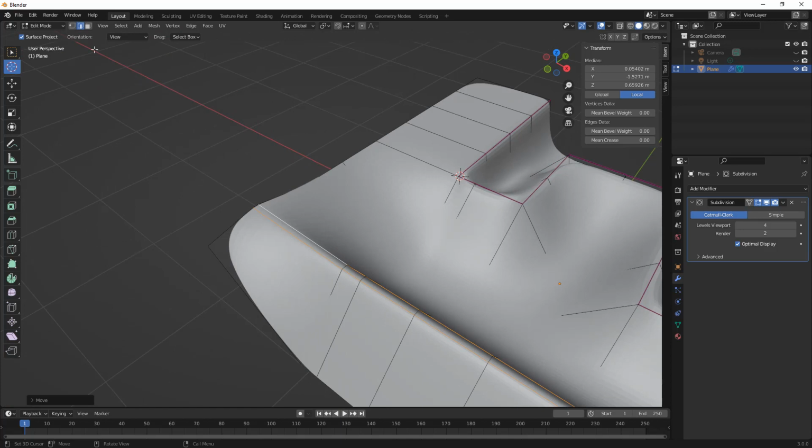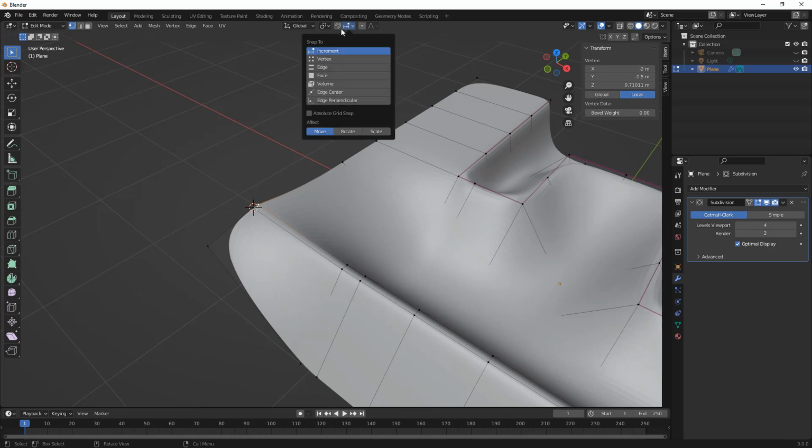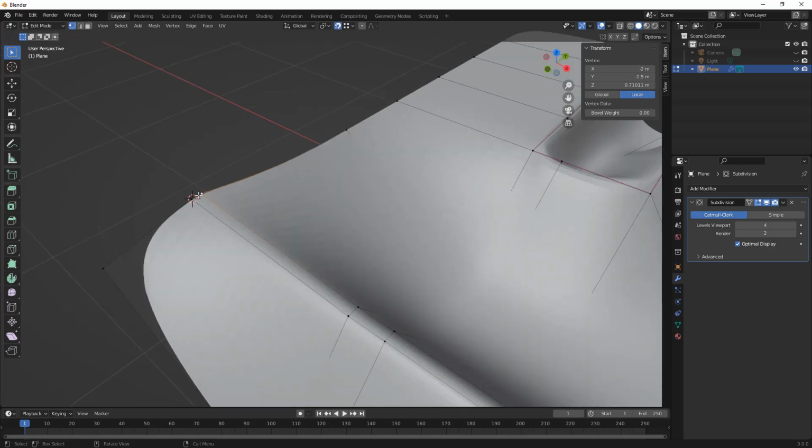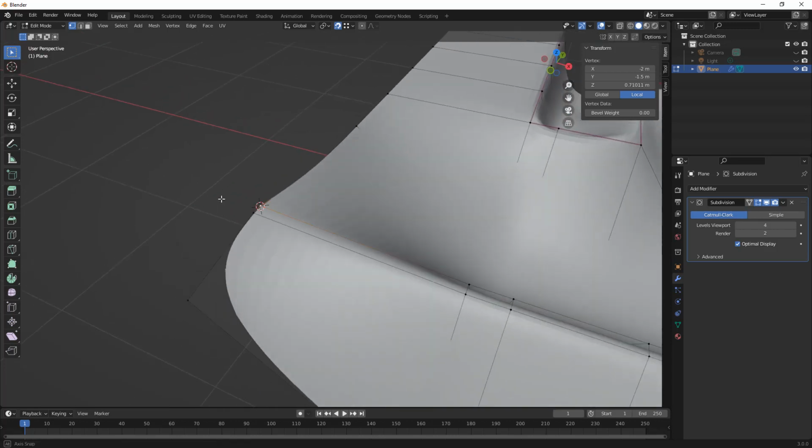So if we wanted to snap somewhere, then we need to make a very specific selection. So I'm going to go back to my selection dialog. I'm going to select a vertex, and now I want to place the cursor there. Well, in order to place the cursor there, I can't just do a Shift and right click, and I can't use the move option because I actually want to snap it to my selection. So the way that we want to make this work is by coming up to this magnet icon, which is our snap tool. Now the snap tool will allow us to toggle on the ability to snap directly to specific entities. So for example, a vertex. We're going to click on this magnet icon to enable it, and then we're going to hold down Shift and right click and snap it to a vertex.